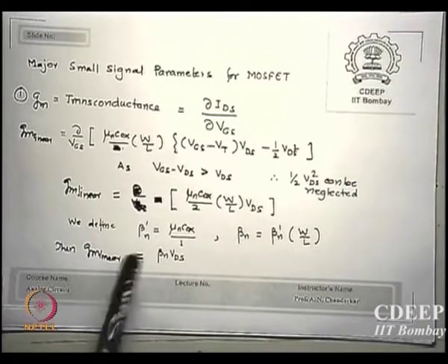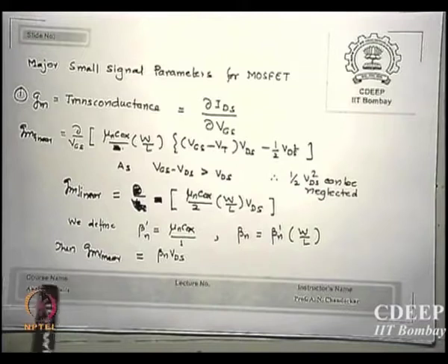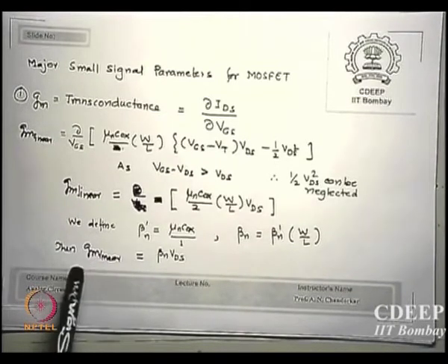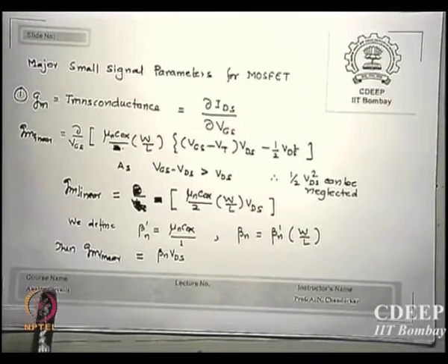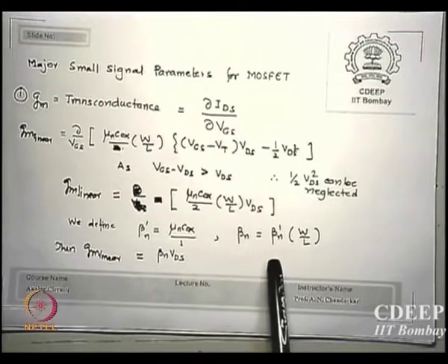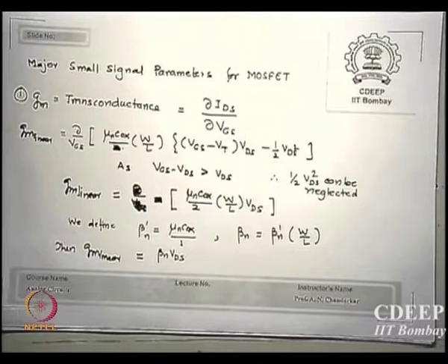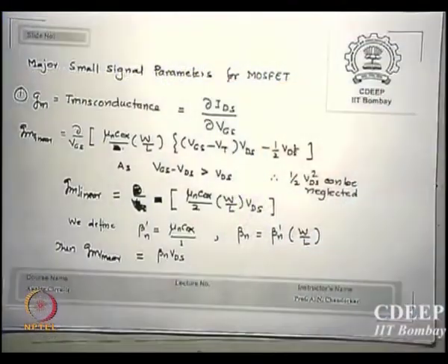Okay, my symbols and book symbols are different. Please note down somewhere. I have been habituated for 20 or 30 years. The constant we use in all books, Kn or Kp, I write beta n and beta p. Is that correct? Kn dash is Bn dash, Kp dash is Bp dash. Beta n we define as beta n dash into W by L. That is just to shorten the expressions, because otherwise every time we would write mu Cox W by L, we just write betas. What units can you think beta has? Can you suggest from here what will be the unit of beta?